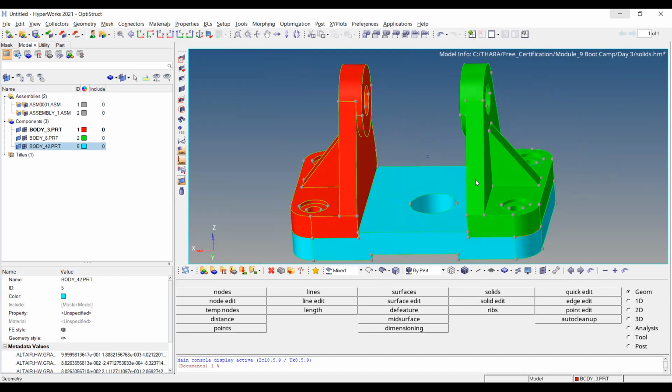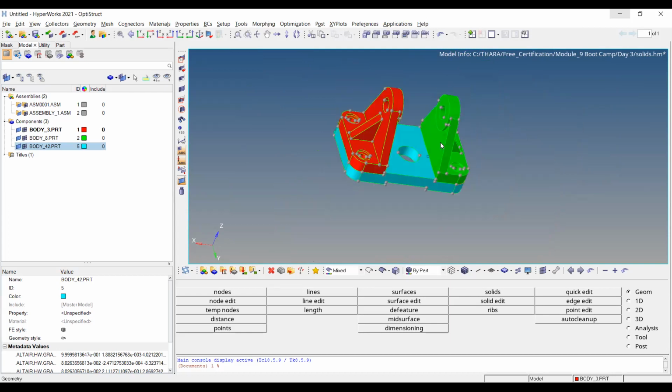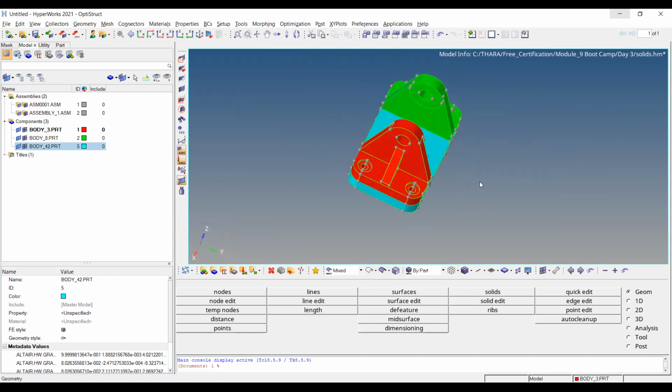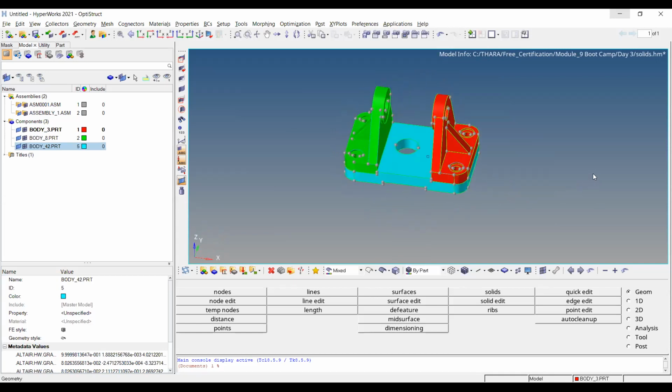The same way how we selected the 2D elements, choosing the elements will depend on the project requirement, the time, and the type of analysis we are doing. Sometimes if we don't have time, for this component we don't have much time to mesh it, or else we need urgent results for this component. Majorly in the CAE industry, there is a requirement of urgent results for all the components. That time what we will do, we will choose tetra elements instead of hexa elements.